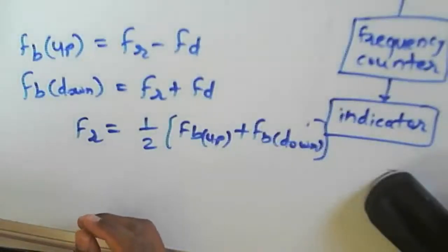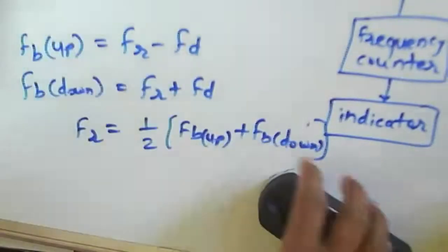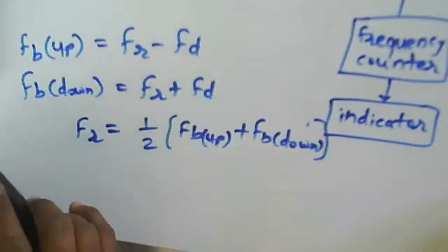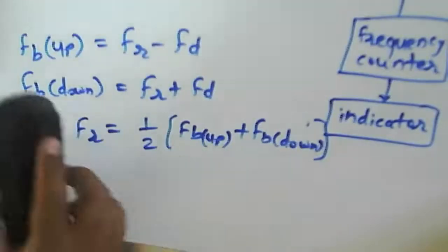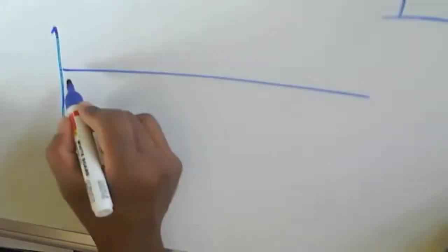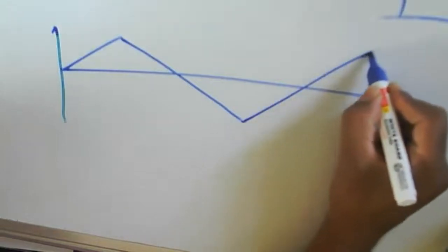and through that we can find out the range of the object using this difference in the frequency. So in terms of a graphical representation of this Fb and Fr, Fb up and Fb down, we can write here when we transmit the signal, because we have a transmitted signal that is a triangular one. This one is your triangular signal now. In that case, we will get the echo here.